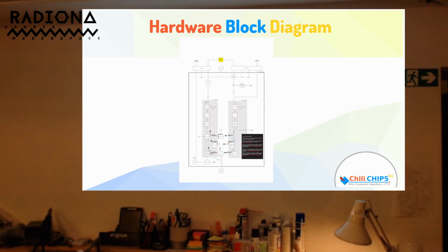This one is a CIC filter as a down conversion. Because this data is going into the CPU next, we cannot take this data at 65 megasamples per second. We need to lower it down. So far, we have theoretically established that we are going to use 10 kilohertz for that. Here we have the low-speed debug memory.